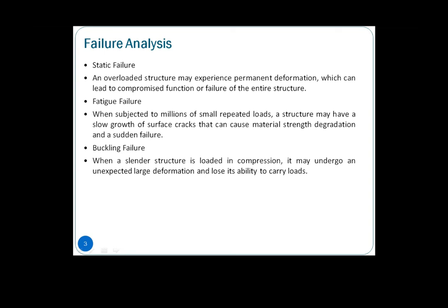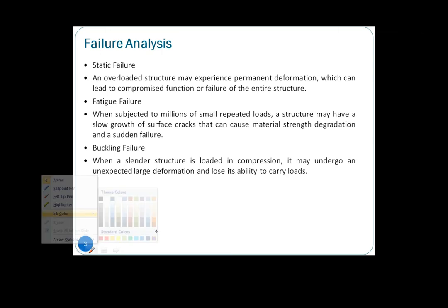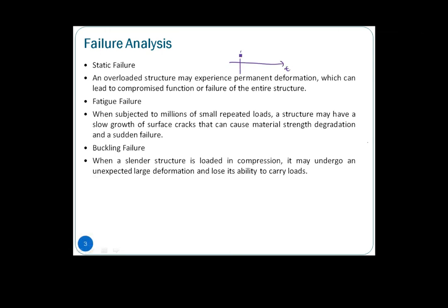If you look at it over time, for static, let's say your P is your load itself in Newtons, then over time it stays constant. Right. So fatigue is subject to a dynamic load, then probably your P over time varies. Subject to dynamic loads, it will also cause failure. So this failure we categorize as fatigue failures.